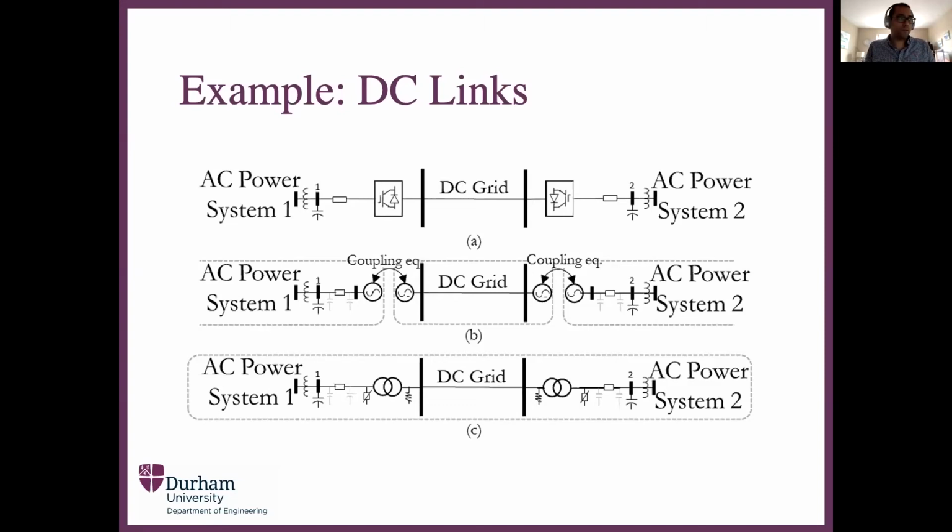Now, there's a little bit of a technicality here, because in DC, you do not have a type of power that you do have in the AC. And our model is able to make that distinction automatically. So in DC, you have everything that you expect to have in a DC grid. And in AC, you have everything that you expect to have in an AC grid, without the need to add these extra coupling equations. Those coupling equations are embedded in our model automatically.